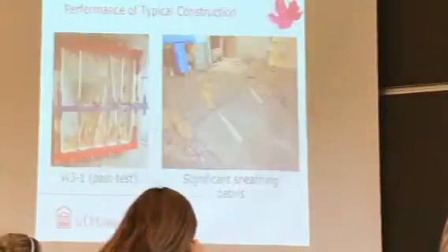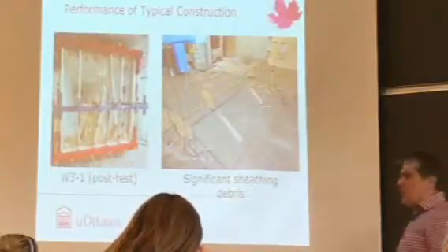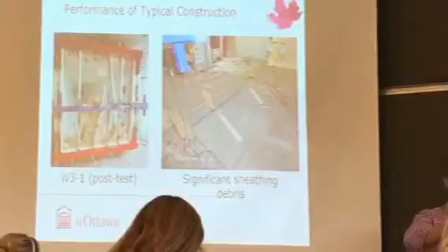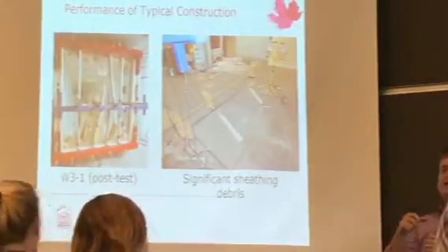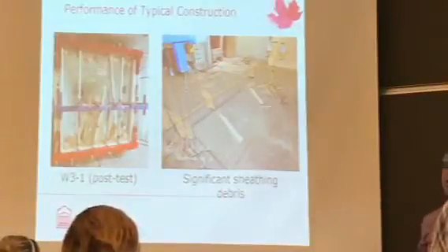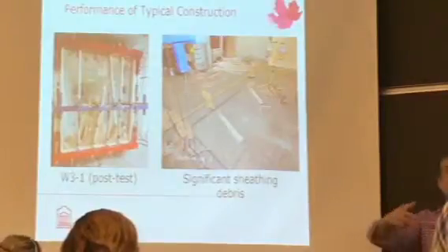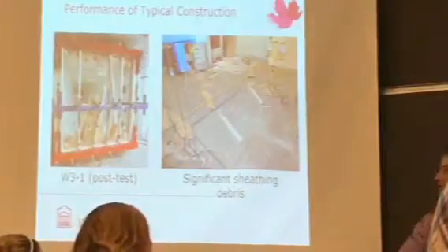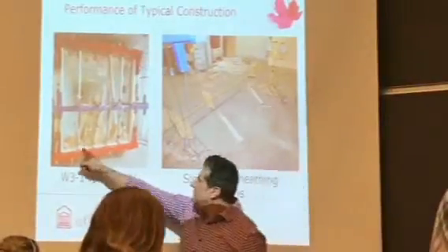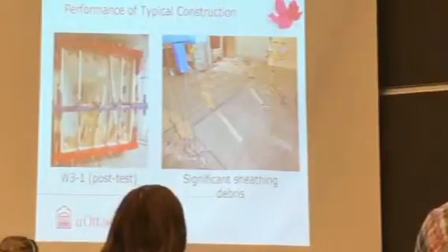So this is the kind of damage that you see. When we did this first, you would test on a smaller level of pressure, and then you would get damage to all studs. The sheathing, the OSB plywood sheathing, was capable of transferring the load to the stud. If we were to just blow it out, you see some of the studs are still standing, and the sheathing failed from between. So that gave us an indication that the typical sheathing might have been a little bit too thin.